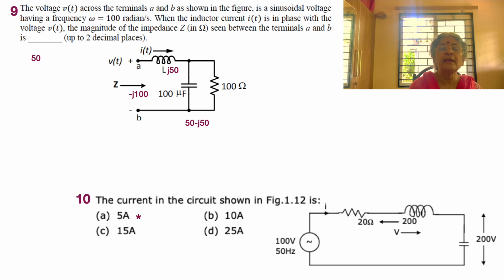And so the only element that is functioning in the circuit is resistive essentially. So we can see that the 20 ohms remains, and the inductor and the capacitor impedances cancel themselves, because there is resonance, as evident from the fact that the voltages are equal. The current in the circuit shown is simply 100 divided by 20 ohms, which gives us 5 amps.